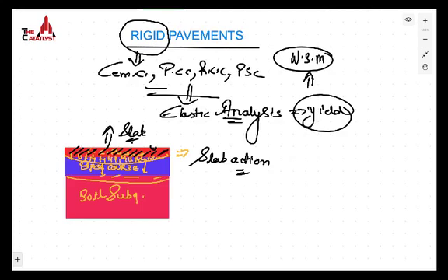It means that the rigid pavement will fail through slab action, but as the load is transferred directly like this, through the slab action, the soil subgrade, which is rigid, will offer some response against that. If you apply load on the soil subgrade, which is actually rigid or stiff, the subgrade will offer a resistance. That resistance which the subgrade offers is known as the subgrade reaction.